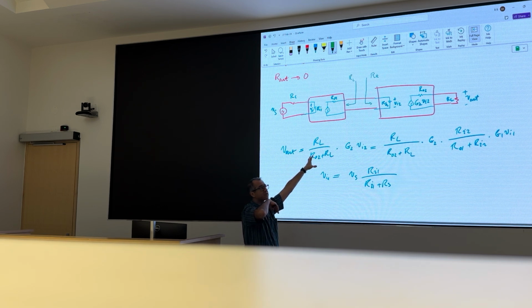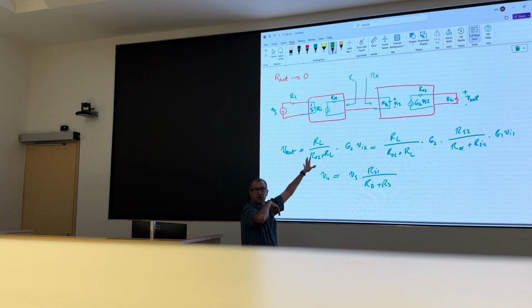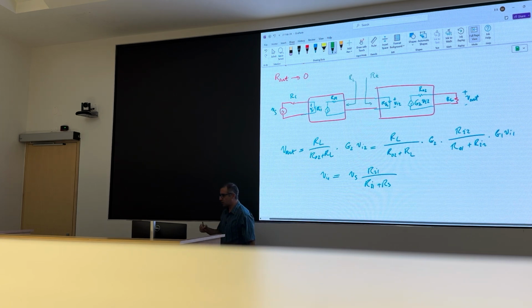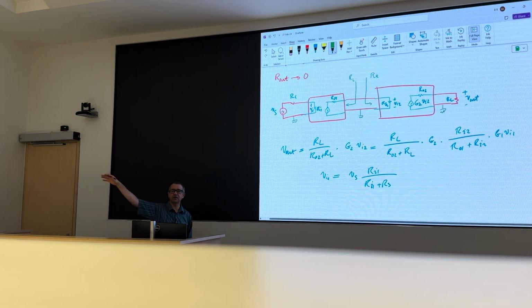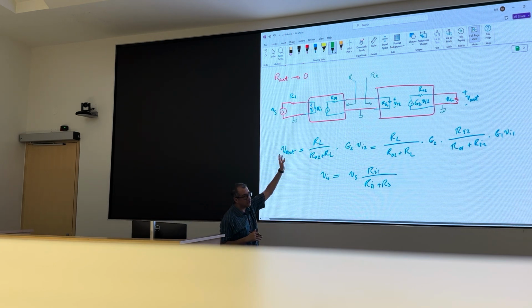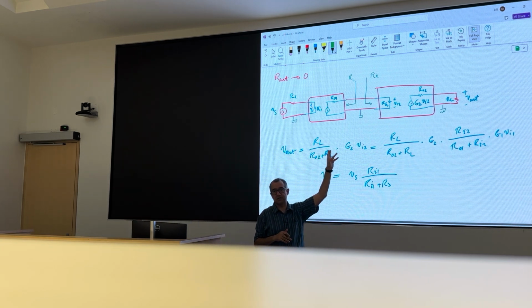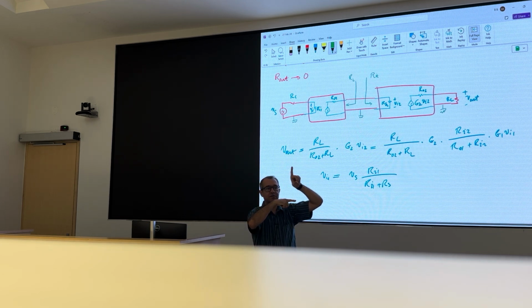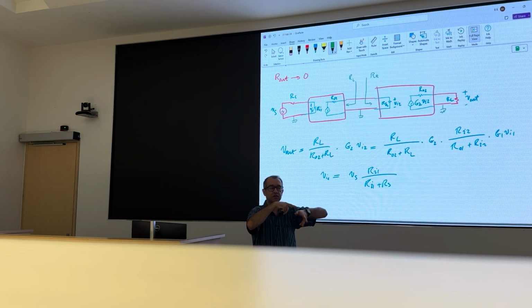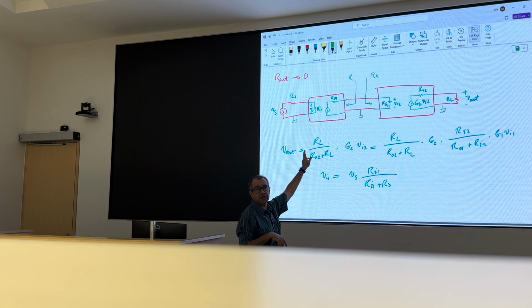This is called an impedance at the node. Why at a node? Well, here is why we call it at a node and not at the cut set. Because usually this bottom line is ground, and it's a common ground between all amplifiers. So I cut just one line to measure resistance. In reality, I know it's a current that goes and comes back. It's a cut set, it's not a node. But anyway, it's called impedance at a node.